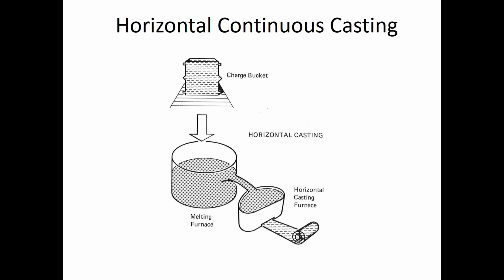Any bad stuff in this melt will float to the top. It is skimmed. Any oxides that develop will be on the top. You don't want that in many of these materials. And these are highly alloyed usually. The casting is slow. It's high cost and high value material.